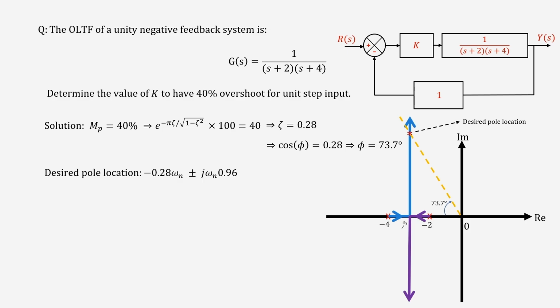So, in this root locus plot, you have the collection of all the closed loop poles. The only thing you now have to figure out is on which of these points I will have zeta equal to 0.28. I can easily find that, because if the zeta equal to 0.28 line cuts the root locus, that is the exact point where you will have zeta equal to 0.28. Not here, but at this point, because here the zeta equal to 0.28 line cuts the root locus. Great.